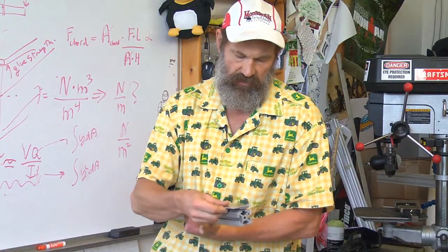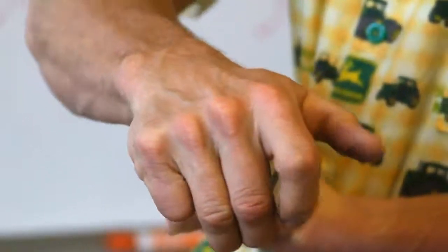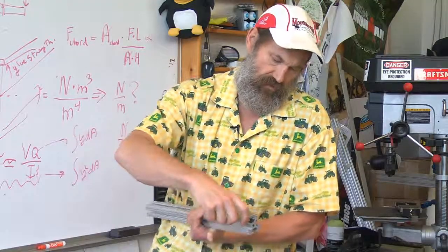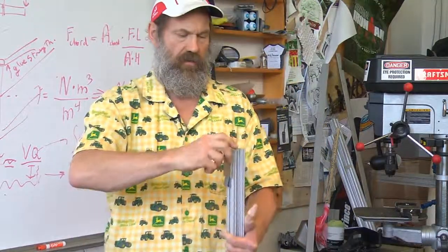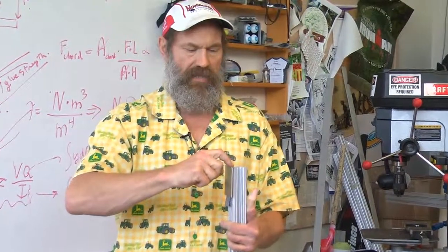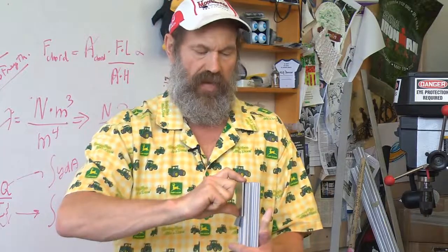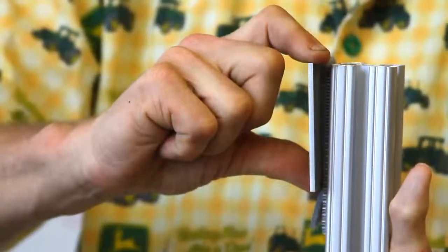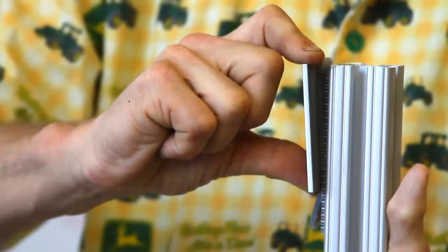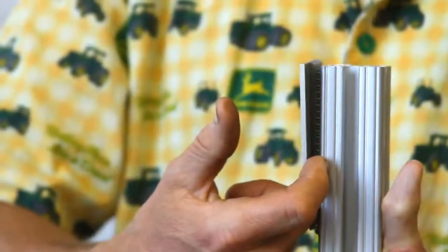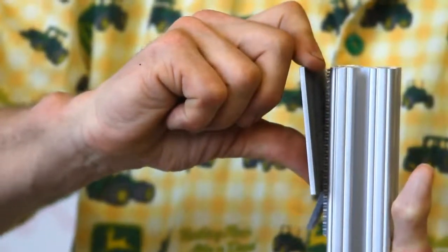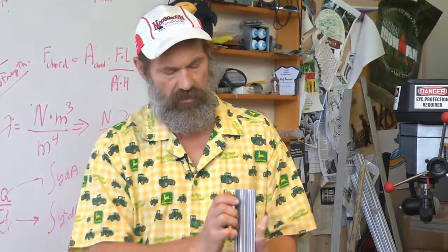The reasoning is that when you're trying to shear it, you're acting upon the entire area at once. For peel, when you start to peel it, the compliance in this one structure allows you to start applying the stress at the very edge. This is almost like a stress concentration issue. These guys are starting to let go up here. They're still attached down there. But as you pull more and more, you win.